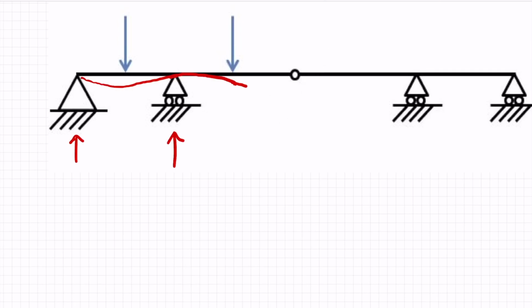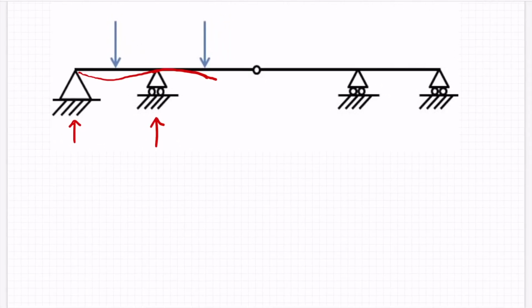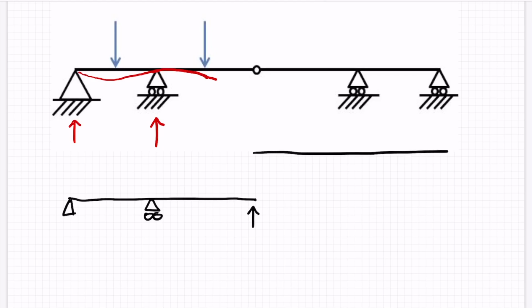Okay, so let's draw the two parts of the structure actually. That's going to be really helpful. What did I say? I said that that's likely to have a shear force going up there, and then on the right hand side, equal and opposite, we need a shear force going down like that.